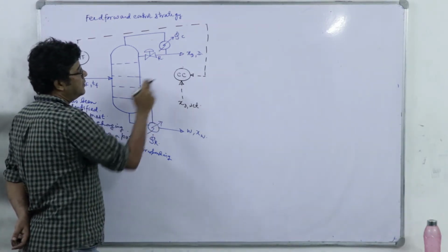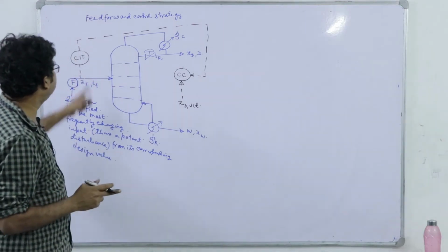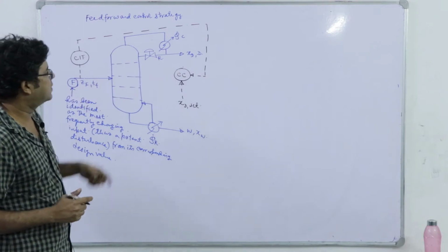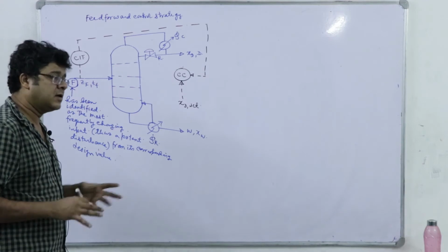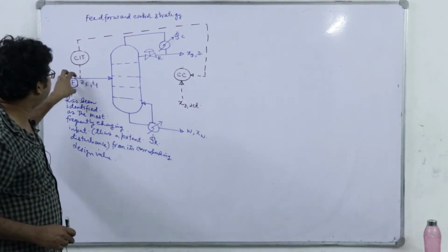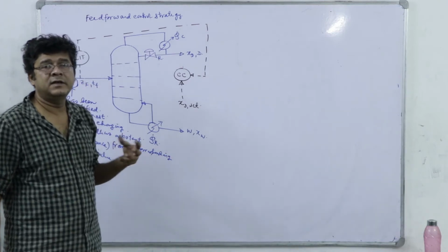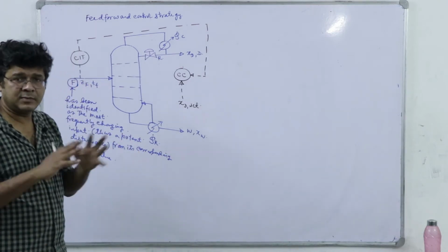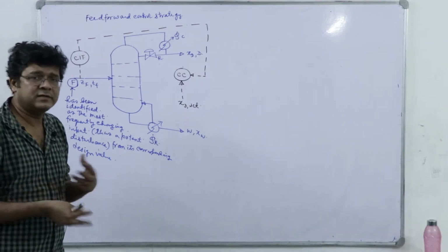So here this composition controller is receiving the current value of the most potent disturbance. It will check the error, and accordingly, if there is a change of the flow rate, the corresponding change that will happen in XD is inbuilt in the controller, as a program or code or model.